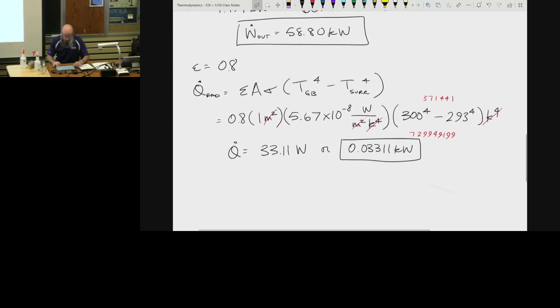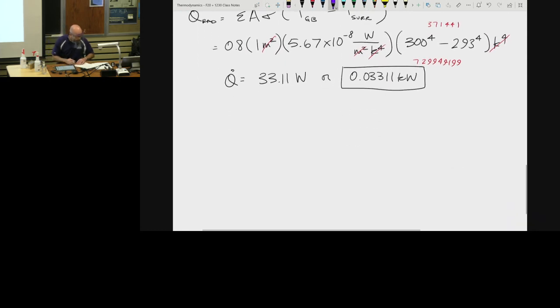I'm getting a lot of questions about a problem on your homework, so I'm going to do a similar problem. We're going to be talking about heat transfer through surfaces, walls. On your homework you have a brick wall and a steel plate on that wall, and you're looking at the steady state heat transfer rate. When it goes into a system, it comes out of the system. It's steady, it doesn't change. Q dot in is equal to Q dot out.